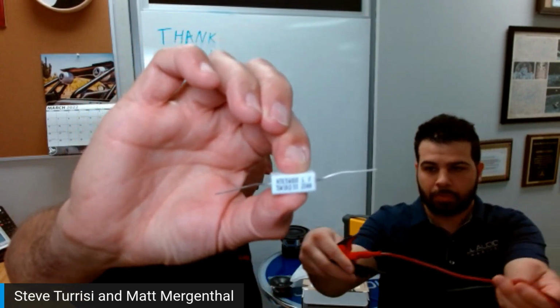And what we'll do here is we'll grab just a multimeter, any old multimeter that you may have. So what Matt's going to do is he's going to measure this resistor. But I want to tell you something. You don't really need to worry about this, because most of the time when you're looking at impedance measurements, it doesn't matter the ultimate value. What you're looking at is a shape, and the shape is not going to change based on the resistor value. However, if you wanted to make comparison measurements and make them consistent from one measurement setting to another, using this resistor value, you can actually have the trace show you the real value of the impedance. So, can you hold that up for the camera, please?